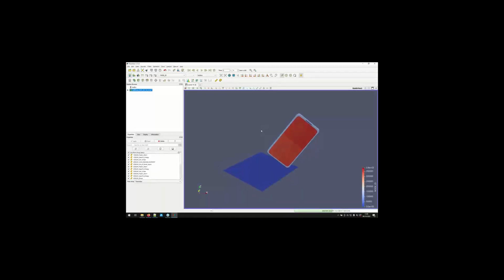So we have some data. Okay, we are engineers. We want to post-process OpenRadioss data. So we have a mesh. This is an unstructured mesh, and we have some fields on the mesh. So how to display the field? You have to use this combo box here. You can see all the available fields here. By default, the node ID has been selected, which is an ID for each node in the model, not relevant here. So let's select, for instance, the velocity.